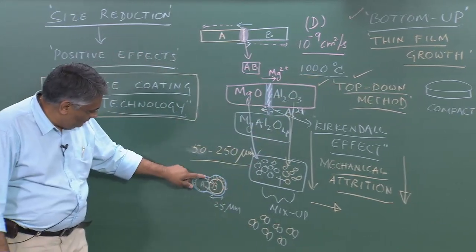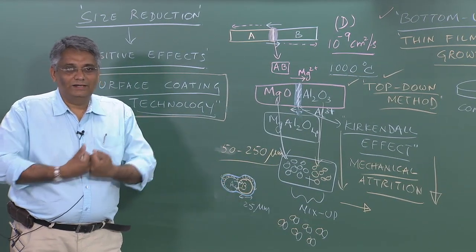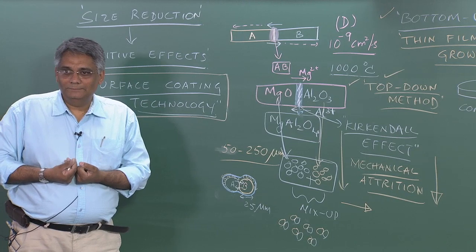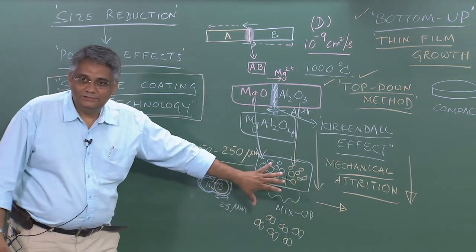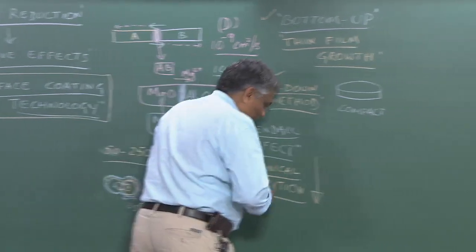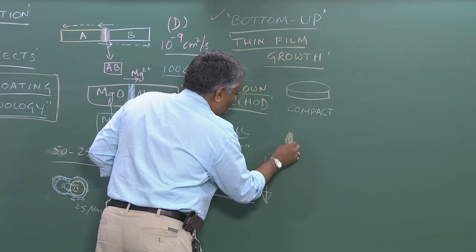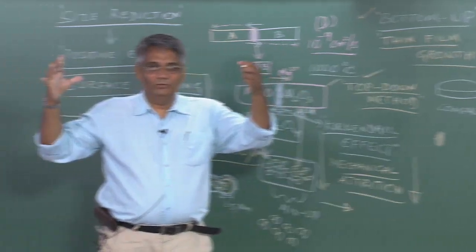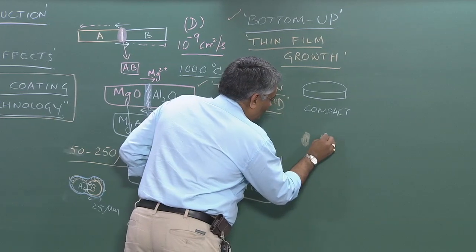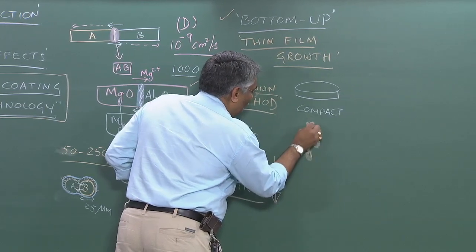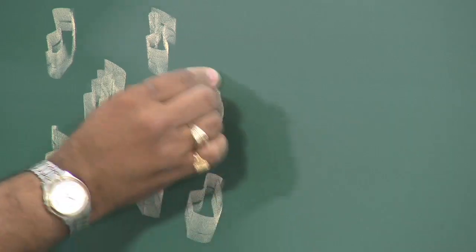So it's a surface melting that happens first, leading to particles getting attached to one another, and since you have a large number of these particles, you have a number of nucleation sites. So the nucleation starts there. A few particles coming together, and you have a nucleation. So multiple nucleation sites, and these nucleation centers start growing.